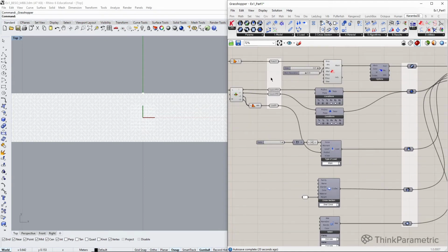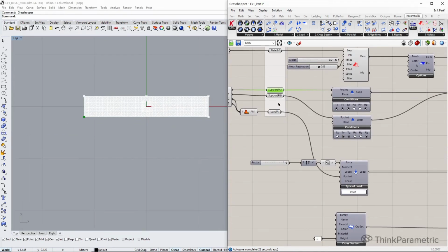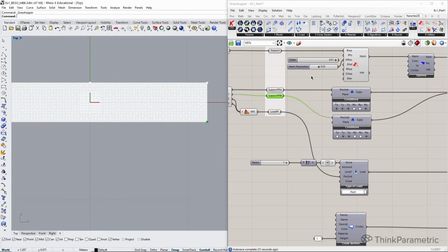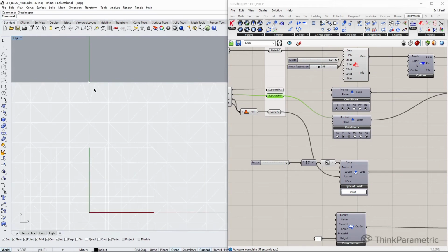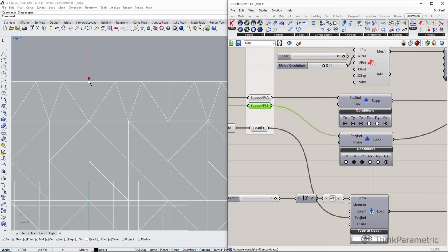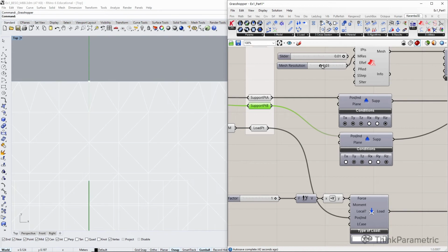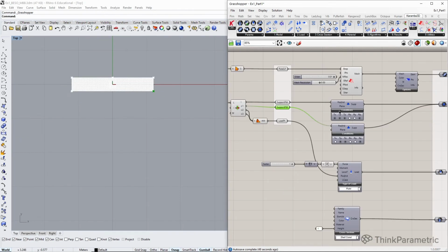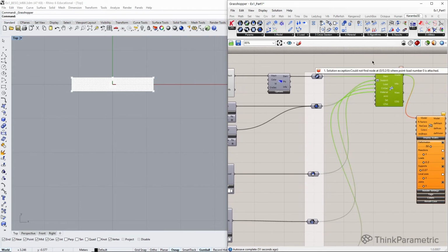These corner points always lie exactly on our mesh, independent of resolution. But this point in the middle, as you see now, is exactly in between our triangles. Probably with 4 it's exactly here, so it works, but with 3 centimeters the resolution didn't work out and it gives us an error that we cannot find the point load, this point in our overall mesh.